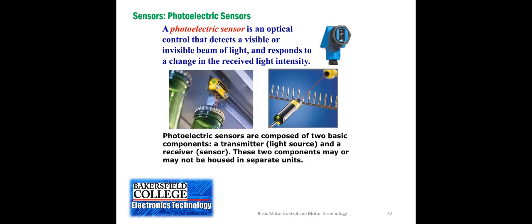These photoelectric sensors do the same thing, but they're just looking for specific points of light that are being disrupted. They often use LED lights, laser lights, or they may use small lasers themselves. That's because those devices can really focus a beam of light in a very sharp point, and that can mean increased accuracy rather than just using a regular light source. Even with a lens, we might not be able to get that fine of a point.